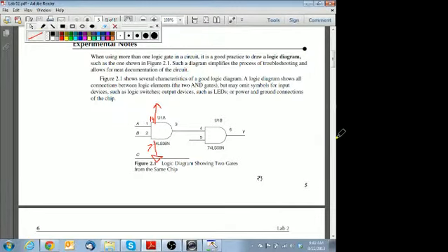You can add it there. Yeah, you guys have to have a resistor for the LED, just like yesterday. You can do 330 or 500 or 1K, something. Just limit the current with a resistor.